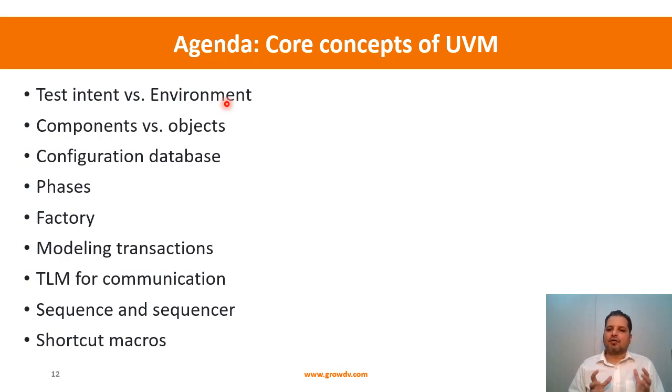So you write the environment like a programmable engine, and don't put test-specific functionality in the environment. You have a series of tests; common functionality to implement all of those tests you put in the environment, and the actual test-specific sequences that you need to do, you keep separated. This way the whole environment, a lot of components and everything, becomes reusable. If I tie everything down to the specific design that I'm verifying, then we cannot reuse it somewhere else. So the common functionality is extracted and put in the environment. Okay, that's the first thing.